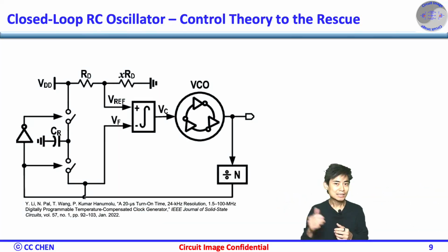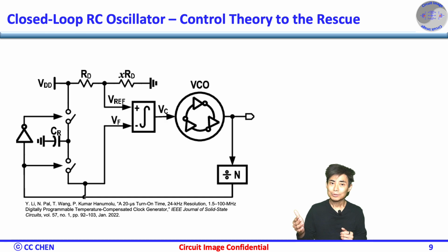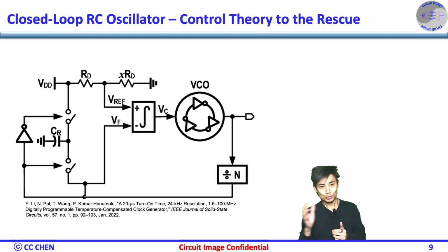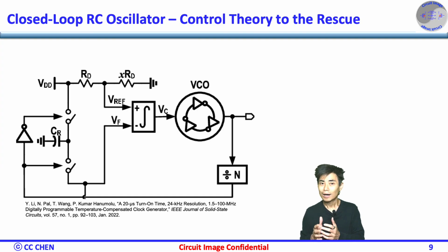We borrow the concept from a PLL design. If you can measure frequency via frequency to voltage conversion, then compare it with a stable voltage reference, you can use the feedback loop to lock the oscillator. The frequency becomes a function of known quantities: resistor, capacitor, divider ratio, not device mismatch. The loop removes the dependency on delay or threshold. Then, how to implement it?